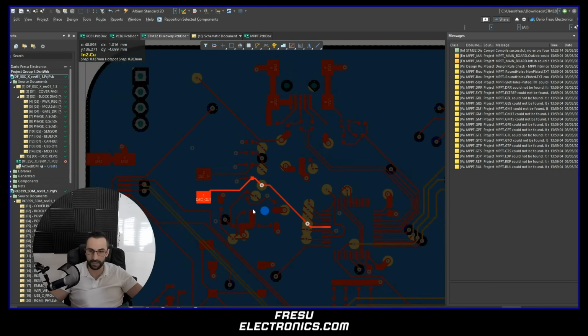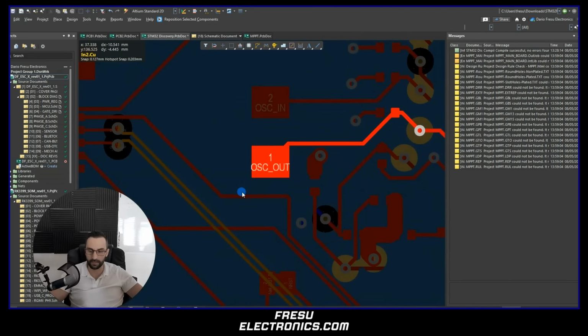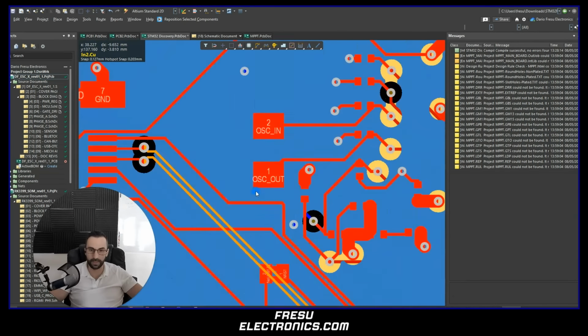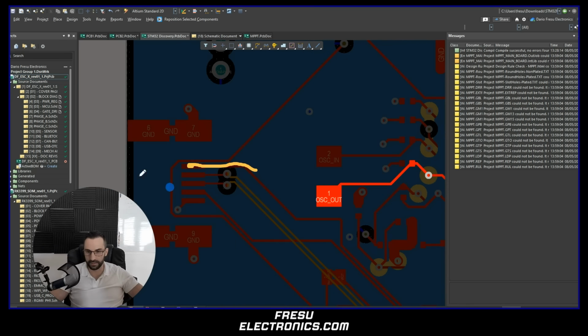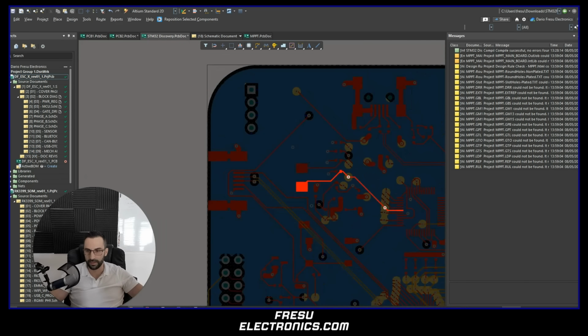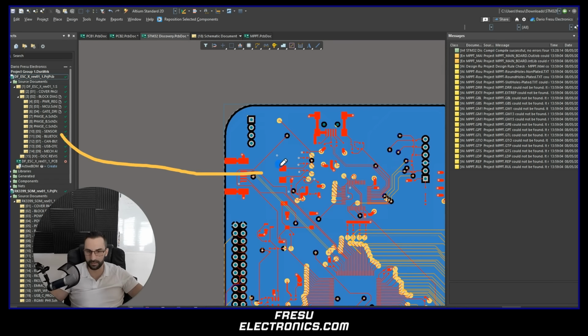So when you're routing, especially clock signals, you want to route them as close as possible to the pin that they're serving. What can happen in here, as I pointed out, is that these traces are very long, and this square signal can couple to other traces. It can even couple to this trace and then reach here, and from there it can reach this point, but this is also a cable, and then from the cable it can just propagate out.